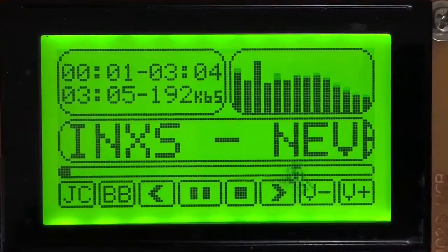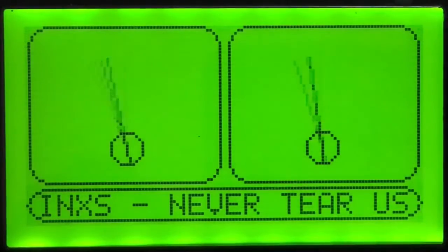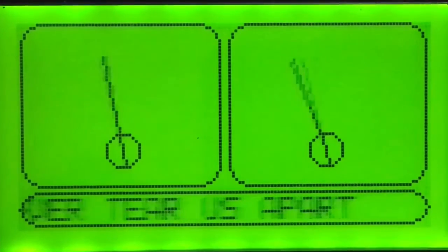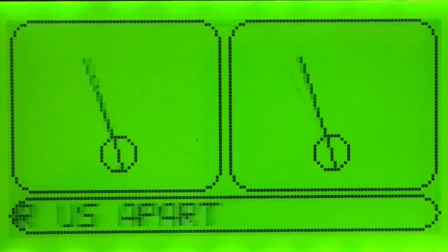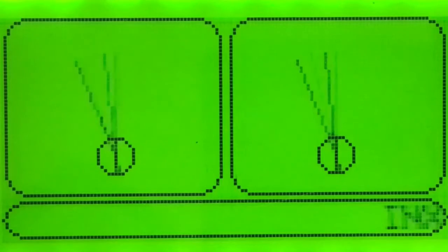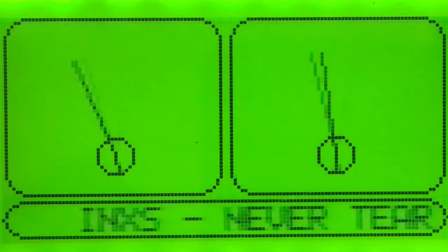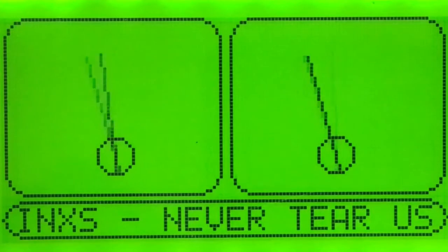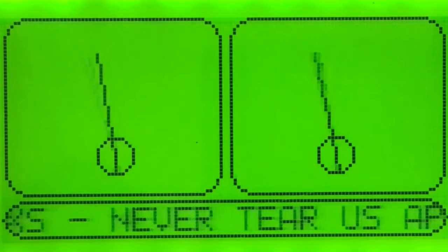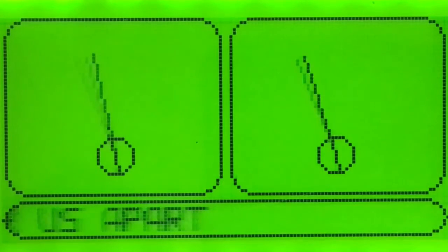I've already uploaded a sneak peek at the analog level meters. This can be achieved because the VS1003B chip answers requests for DAC sample values. This is a legitimate stereo display, unlike the spectrum analyzer, and unlike the spectrum analyzer, the DS-PIC does most of the work for this display. It has to send requests often and calculate averages for the needle positions. The ghosting effect you see there could be avoided. I lost accuracy though when I tried to simulate the needle spring. I had to choose between one or the other, and this one looked more realistic overall.